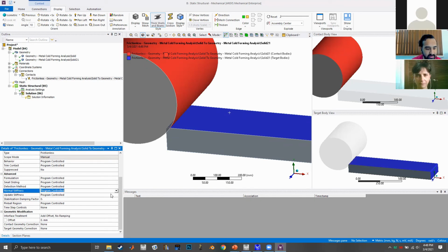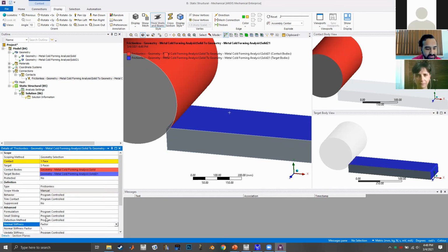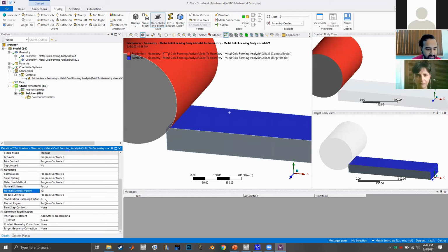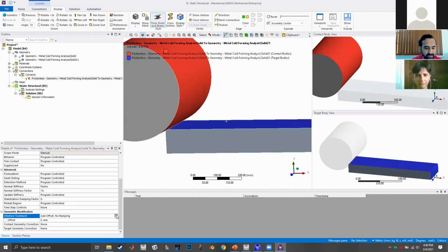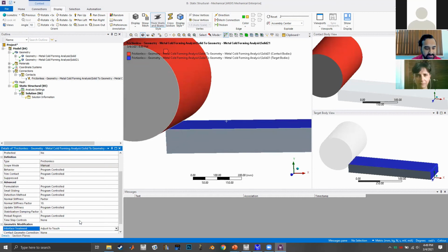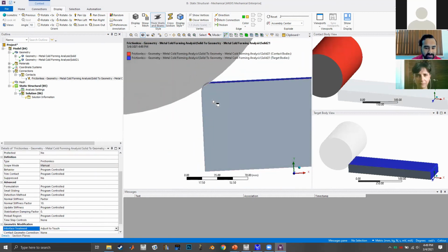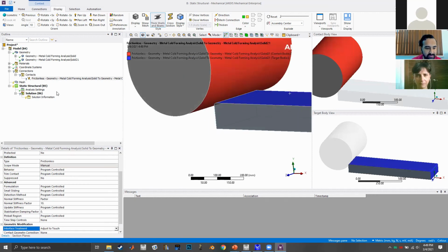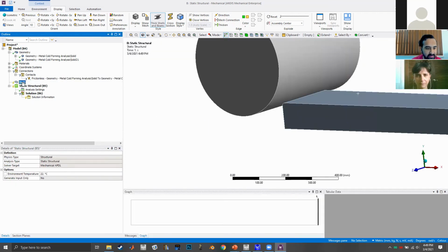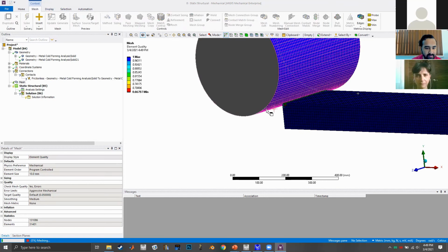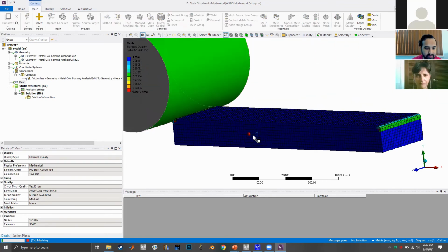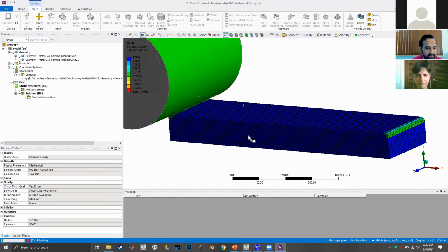So in normal stiffness, let's make this relatively stiff. Let's make this 10. I think an interface driven, so how should it be touching it? We're going to edit this to be just a touch. So ANSYS is going to move our model so it's just barely touching this piece when it starts the simulation. All right.